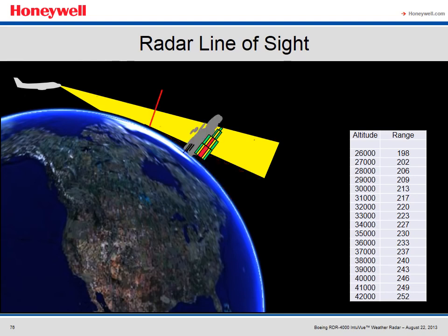Anything that shows up beyond the radar line of sight is significant and should be monitored. But at this distance, deviation decisions are not being made. The weather at this range should be viewed on a more strategic basis. By the time the aircraft reaches these cells, they may have moved into or out of the flight path, increased or decreased in intensity, or completely dissipated. At long ranges, all the pilot knows is they are worth monitoring.